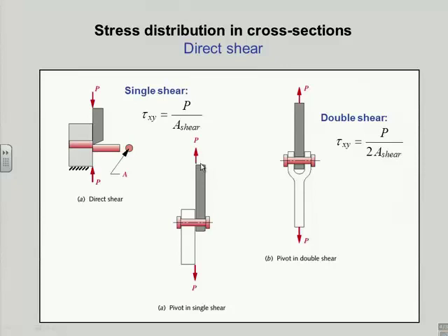And if, in fact, the average force ends up being out here, and even there I have a bending moment. Here I've canceled the bending moment because the two forces are in line. So that's better in that respect. And I also have twice the shear area now for the same size pin, right? So it's P over 2A.